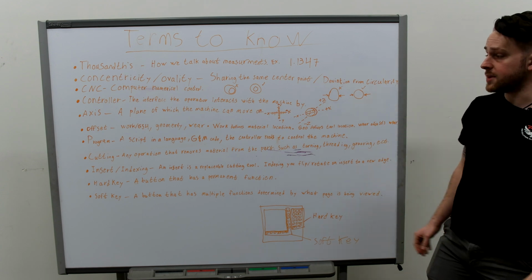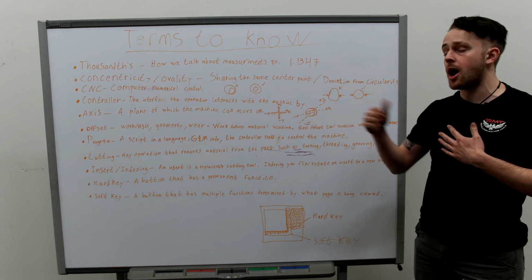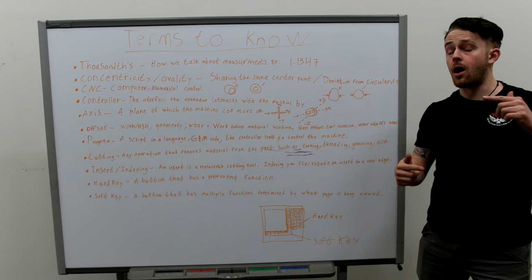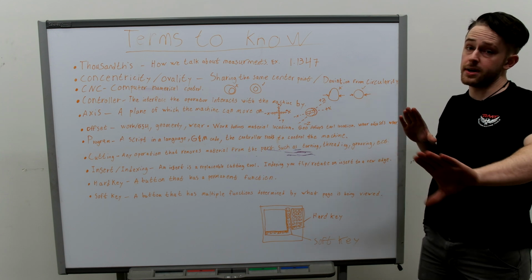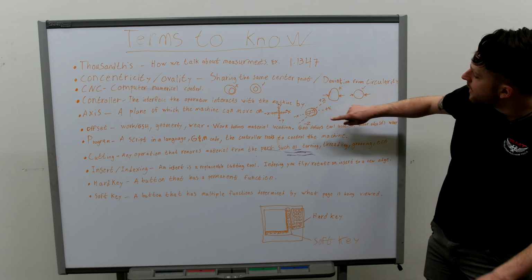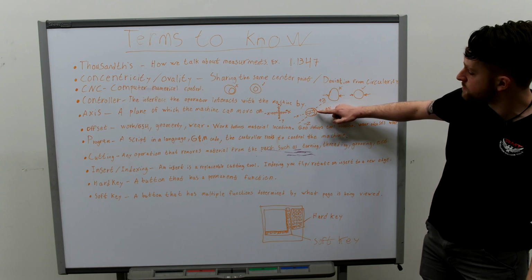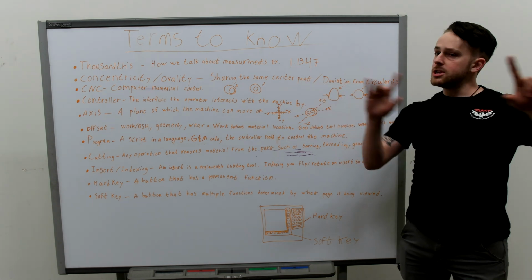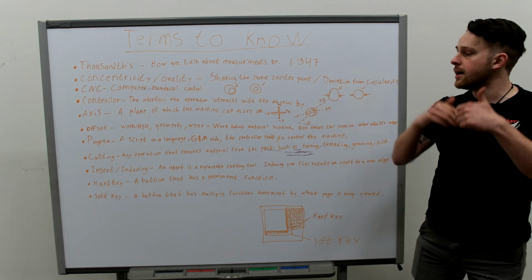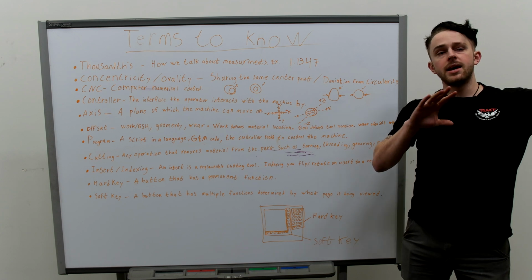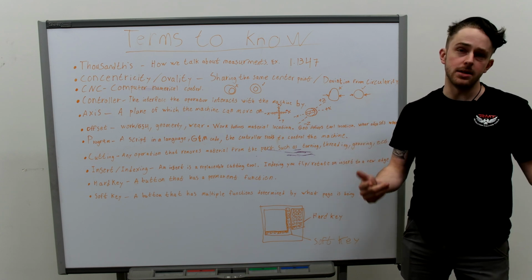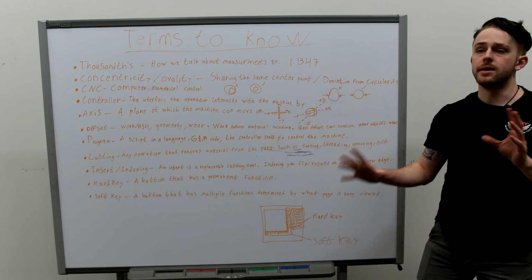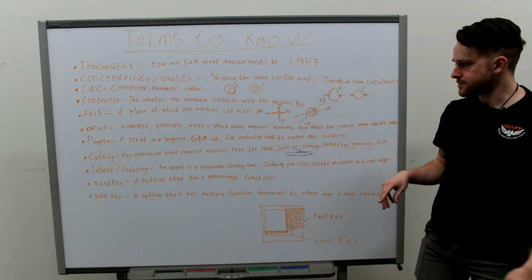Now, the next type is a geometry offset. So this is defining where our tools are, right? Again, the machine knows where it exists, but if I have a tool way on the outside of my spindle and another one that's really close to the center of my spindle, the machine doesn't know where those are until I touch off those offsets and tell the machine where they exist in space, and then it can make the appropriate cuts. This will all be covered in offsets in another video.